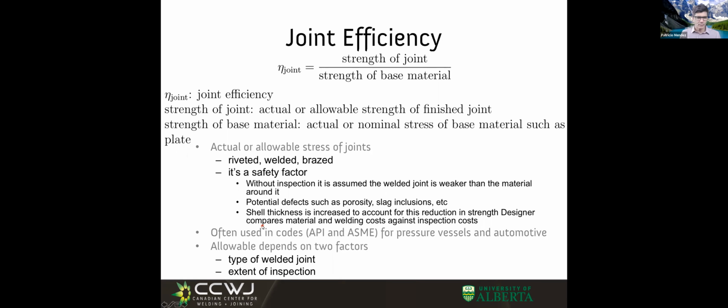An interesting thing about the joint efficiency is that this exact same joint might have different efficiencies associated with it. This is one plate, this is another, welded. If I ask you the joint efficiency, of course, you can test it and you have a number. But the idea is to estimate an efficiency from a design point of view, so you don't need to break things all the time. And these estimations are based on inspection.